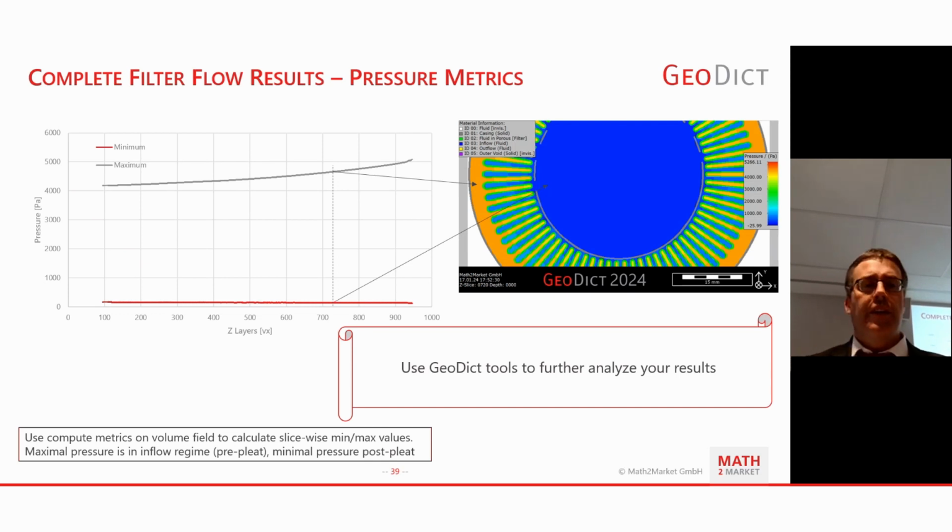But the purpose here would be, for example, if you have a sudden pressure drop somewhere along the vertical, then you can see it. In this case, it's quite simple, but if there's a more complex distribution along the vertical axis, you can see that there's maybe a higher pressure drop, there's a lower pressure drop. And then you can also say, okay, there is a higher maintenance need where the higher pressure drop is.